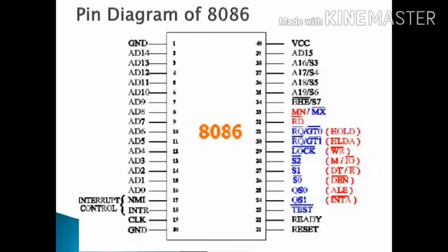In 8086, it is used to send out the address for accessing input output ports, and this information will be 0 during the T1 phase, because input output port addresses in 8086 are only 16 bits. If you remember the physical address calculation formula, we extracted the 16-bit addresses from the segments and added an implicit 4 bits to make it a 20-bit address.